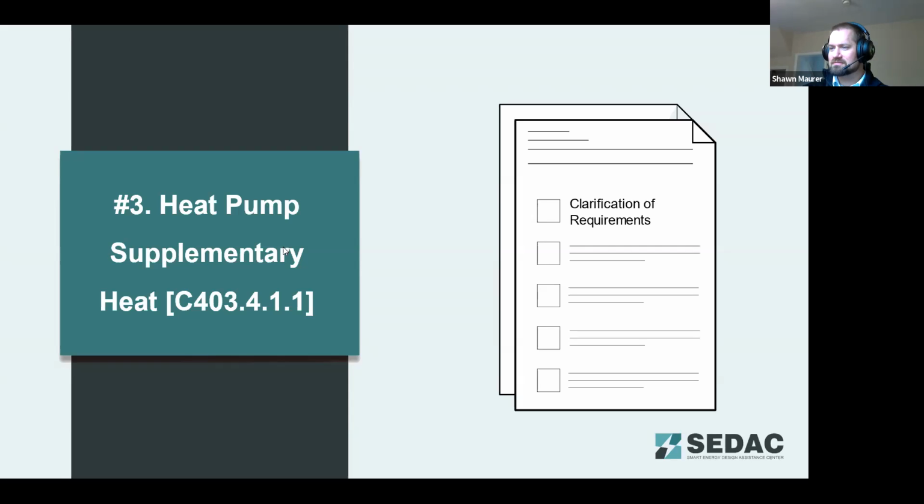So for our first question, all of these are correct answers. All of these systems, and remember, it has to be a 100,000 square foot or more building. The entire HVAC system needs to have fault detection diagnostics built into it. So the central plant needs to be monitored, the economizers, individual zone controls. If you have small pieces of equipment serving small sections of the building, they're still part of that entire facility. Those would all need to be monitored and have fault detection diagnostics built in.